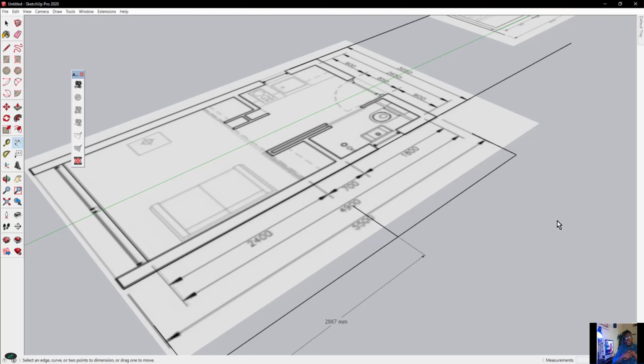So the point that I just showed you a while ago is where, yes, if you scale your page or your drawing, put it in SketchUp and you eyeball it, meaning you put the mouse where you think the line is and then draw the line, you will not get an accurate measurement. Now, the only time you do eyeballing is when you don't have a measurement.